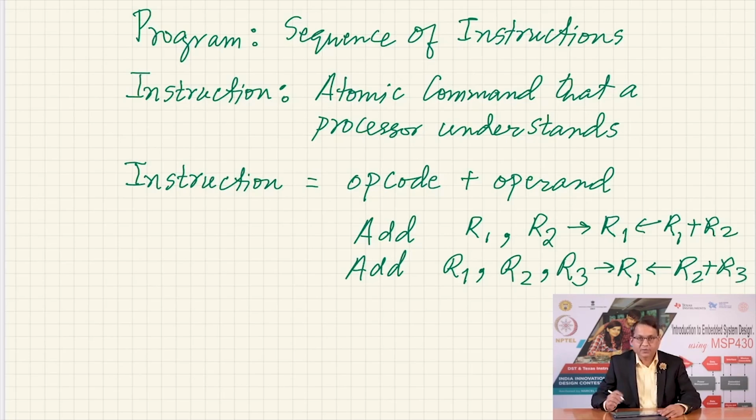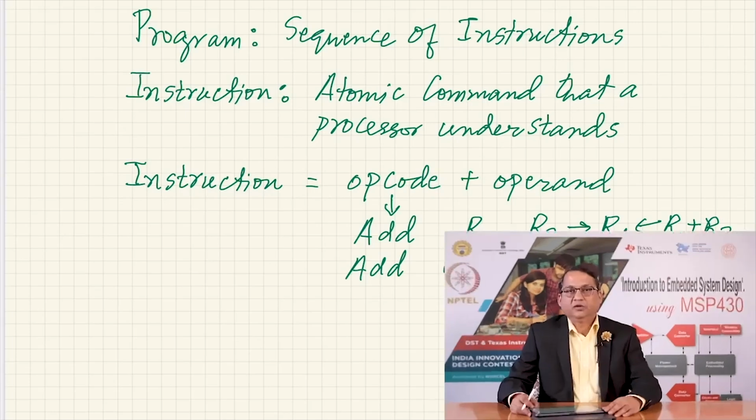Whether it is of the first type or second type would have a lot of bearing on the size of the instruction. But needless to say, the operation to be performed is described as the opcode, and the operation to be performed on what numbers is the operand part of the instruction. And this is where things can take large variety, lead to different types of instruction set architecture.